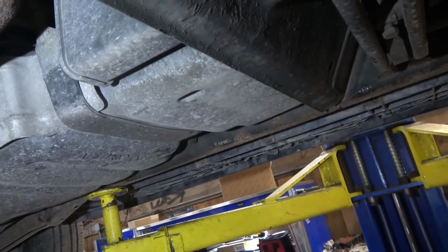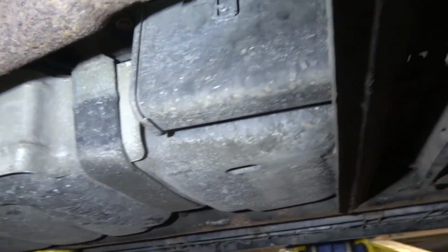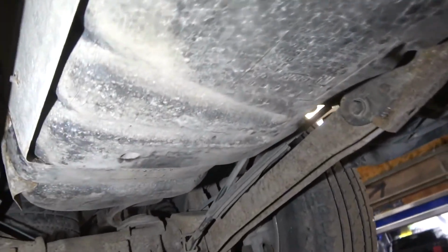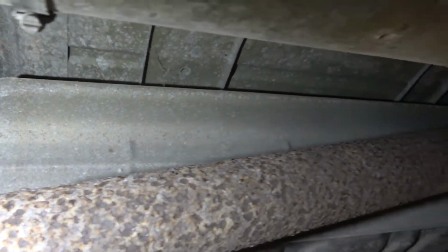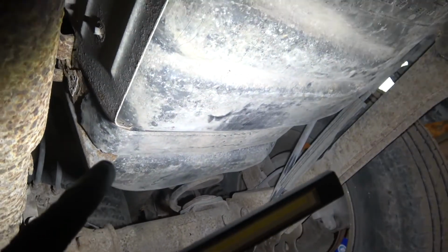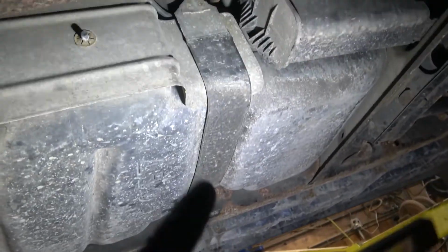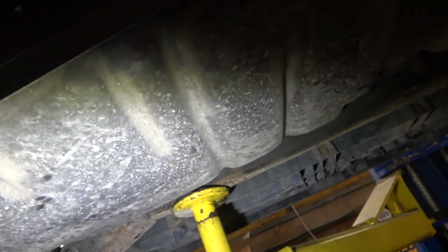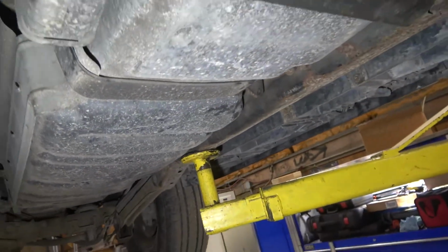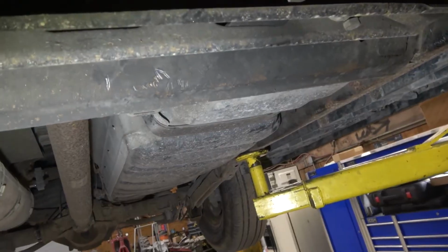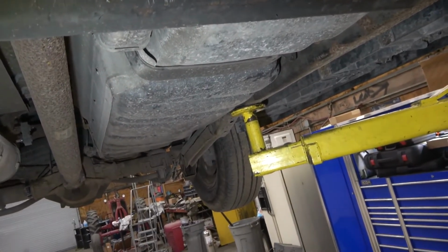We are here under the vehicle. Here is our fuel tank. This is the charcoal canister. This is the fuel tank right over here. Now the fuel tank pressure sensor is up there. It's above the tank, so I'm gonna have to undo these fuel tank straps. There's one over here and another one right over here. Now we don't have to remove the fuel tank completely, but we have to lower it, okay? The fuel tank has to come down a little bit. So I'm gonna lower the fuel tank off camera and then I'll bring you guys back up.